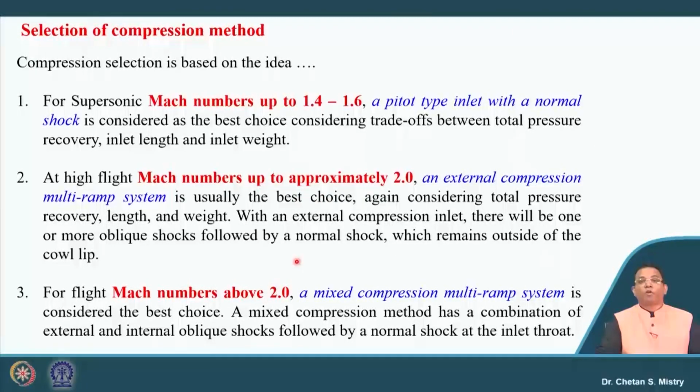Suppose we are talking about Mach number above 2, then we need to go with the mixed ramp kind of configuration. It says mixed compression multi ramp system. That is a little complex, but yes, people are using this for special applications.